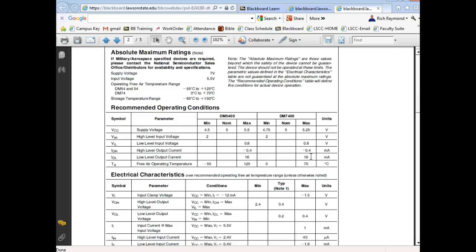Well, you could. So of course, what you're doing is shooting for price. If you're not shooting for speed, then you're shooting for price, right? So it's going to depend on what you're doing, and the bigger the circuit is, and the more logic that the signals have to travel through, the more likelihood you're going to use higher speed chips. Because every time you go through one, it adds a delay.